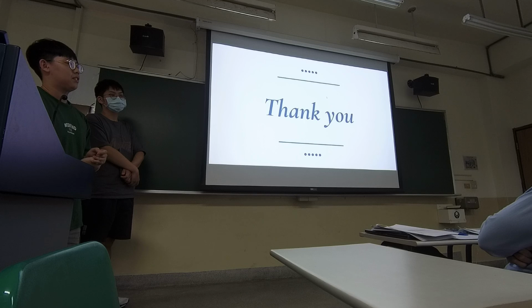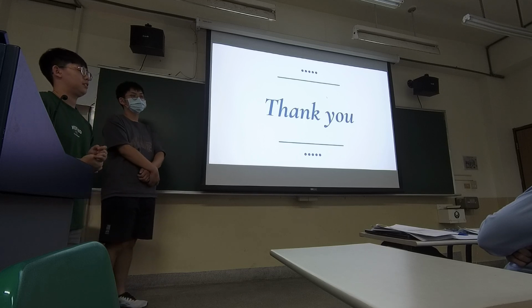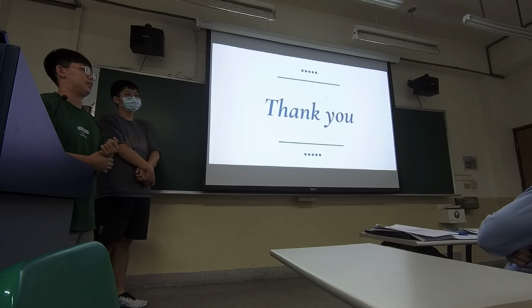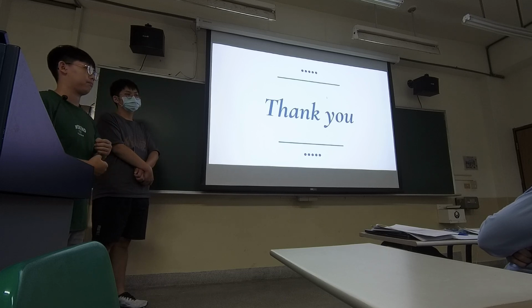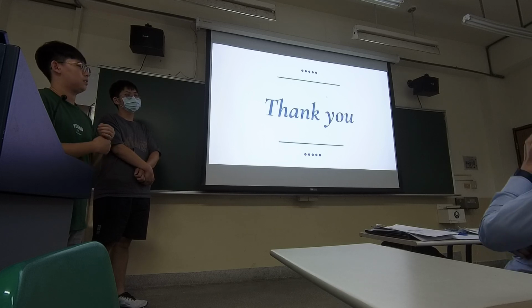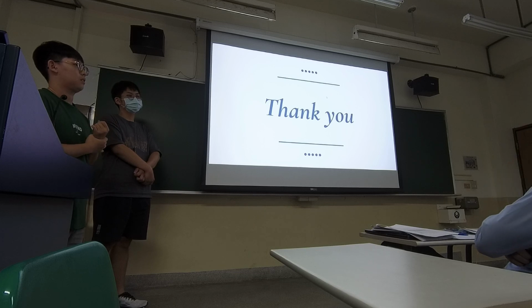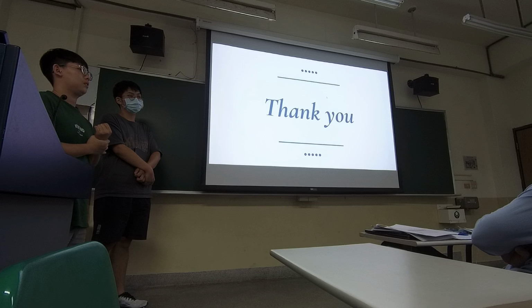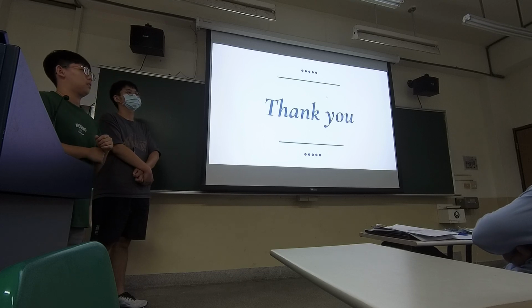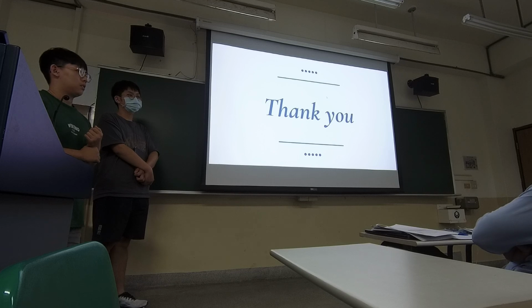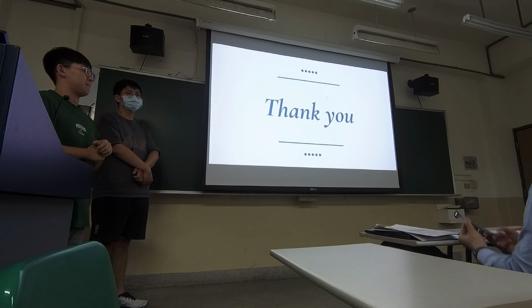For example, in some of the previous research I saw, in the production line, sometimes they want to pick up something from the conveyor and then put it in a box. Because the object on the conveyor is moving, you may need some kind of vision-based tracking system. So it's like a coordinate matching between the camera and the robot position. That is more meaningful, I think.